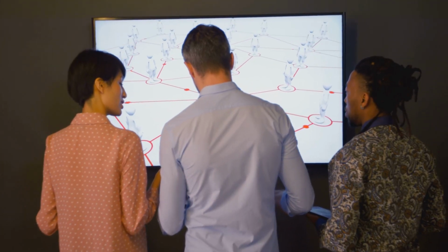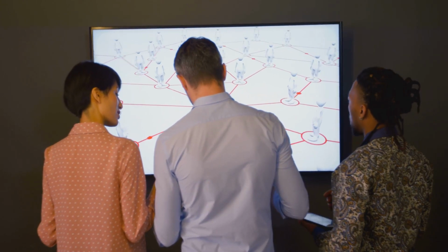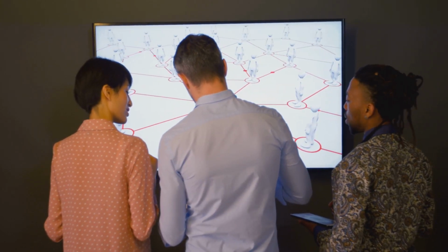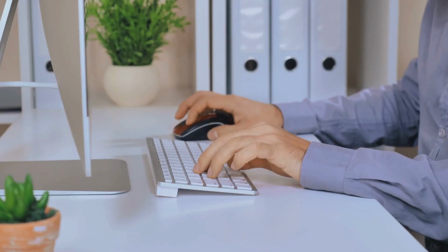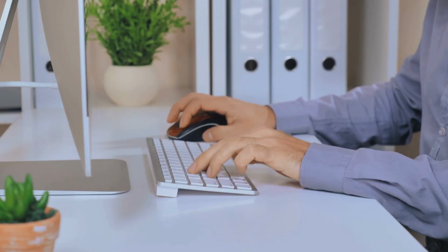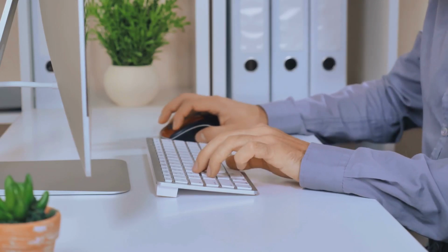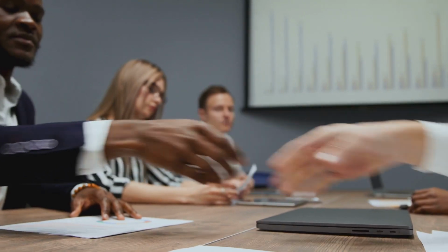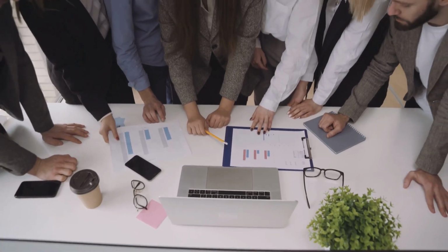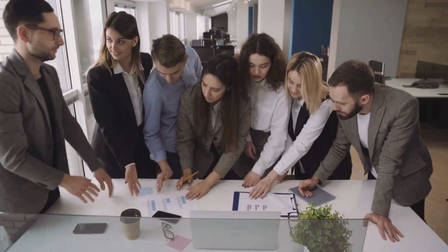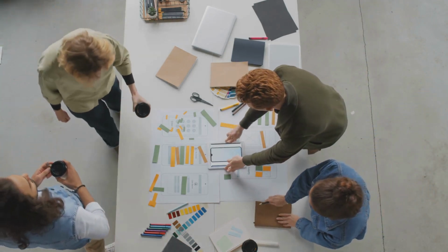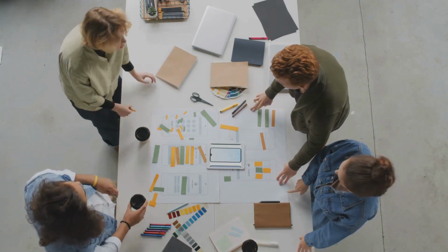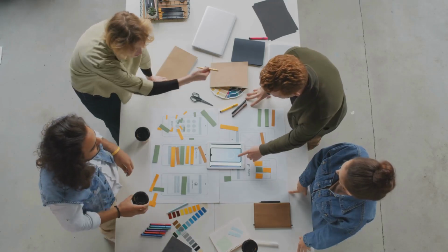We add information flow, mapping how information travels through the system, from customer orders to production schedules. Understanding the flow of information is just as important as understanding the flow of materials. For example, the manager emails a daily schedule to mix wax, informing them of the production targets for the day. And the customer sends a monthly forecast, providing an estimate of future demand. This forecast helps the factory plan its production schedule and ensure it has enough raw materials on hand. Our map now shows materials and information moving through the system, providing a comprehensive view of the entire crayon making process. We can see how each step is connected and how information flows between them.